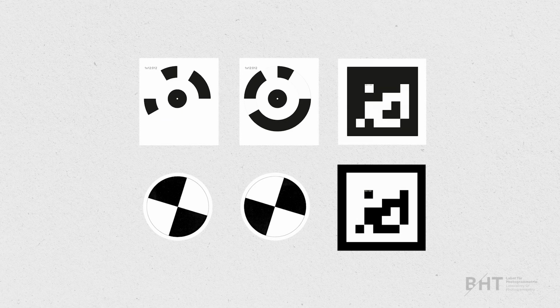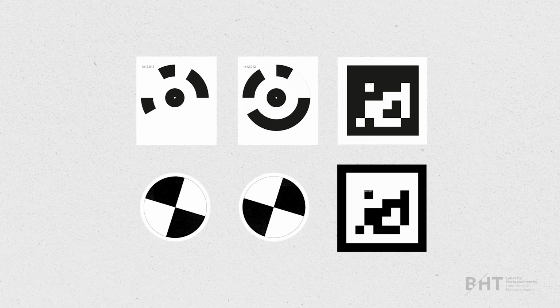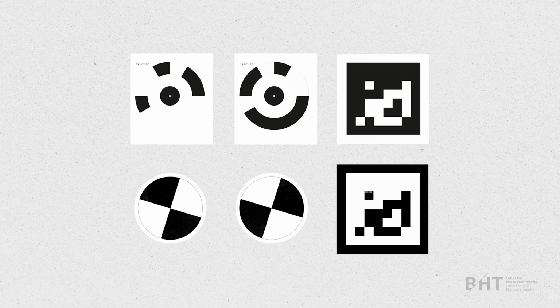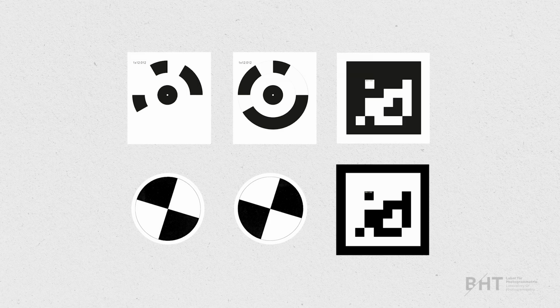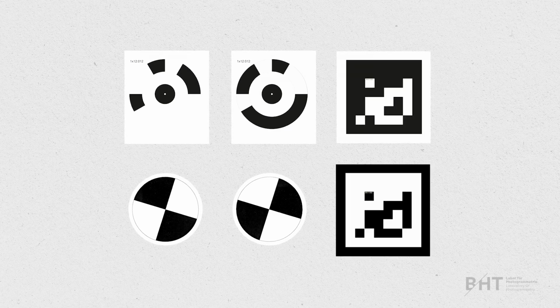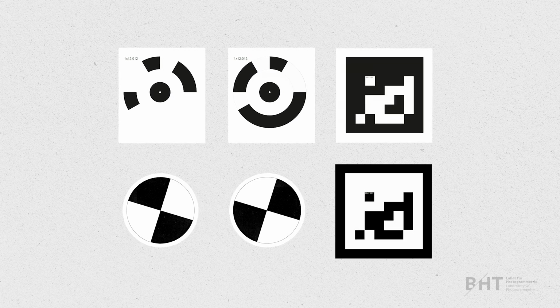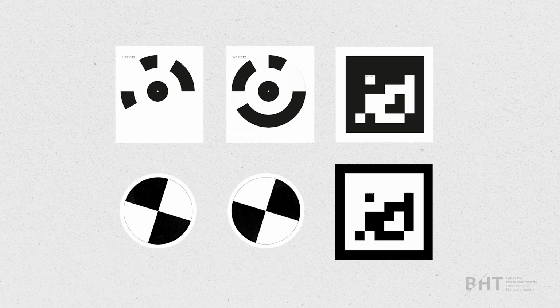Various photogrammetric software products offer templates for printing control points. Such programs normally recognize and measure the control points in all of the images automatically. It makes the work more time efficient. However, care must be taken to ensure that the marks are produced in a size that is big enough to be recognized by the software. We use typical circular markers in our project. The black circle in the center is the actual point and the surrounding ring is a binary code that encrypts the point number.